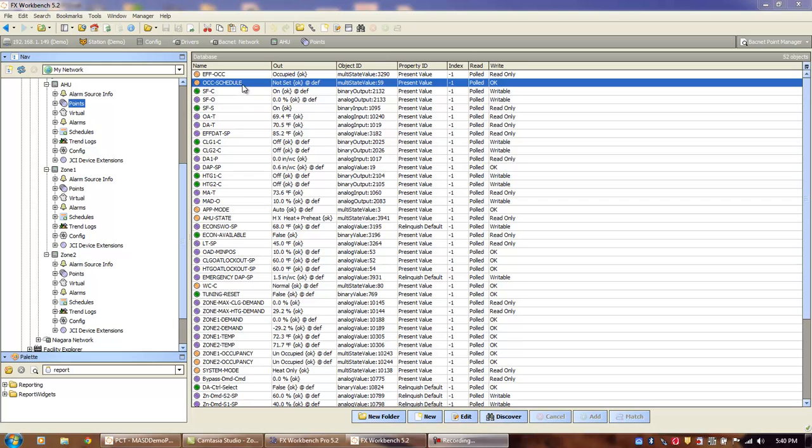So both the AHU and the zones have an aux schedule point. So you'll need to create a schedule in your supervisor and attach them to each one of the zones and the AHU. When the AHU goes to unoccupied mode, it automatically turns off the fan until the night operation is initiated, which is set to have the fan operate at 60 degrees for heating and 85 degrees for cooling.